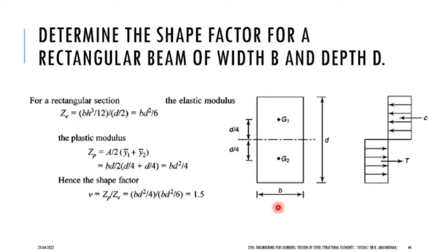If you find the shape factor as 1.5, then you can understand that at this axis, Ixx, you have more resistance towards bending. If for a certain shape the answer is 0.8 or 0.9, and for another shape you get 1.2, which shape will you go for in your structure?